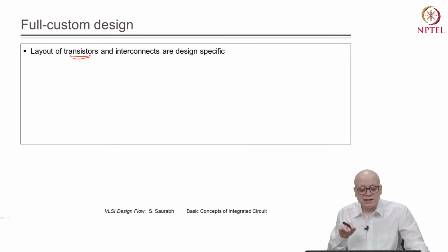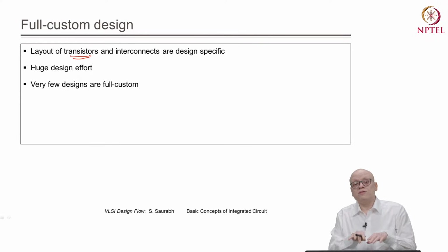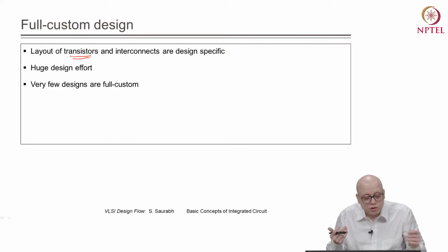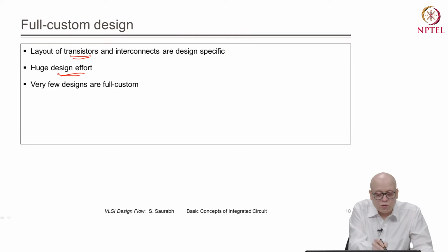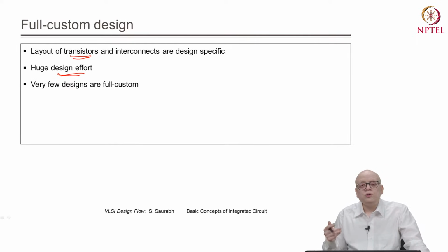So the layout of the transistors and the interconnections, all are design specific. We are designing at the transistor level in full custom design, and as a result, since we are designing at a very low level, we need to make a lot of decisions manually, and therefore huge design effort will be required in full custom design. And there are only a few designs which